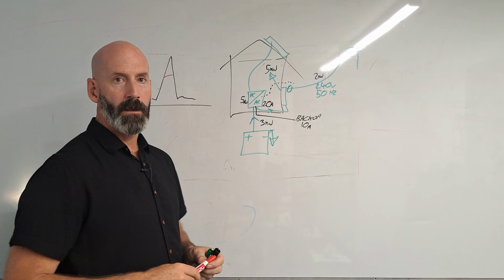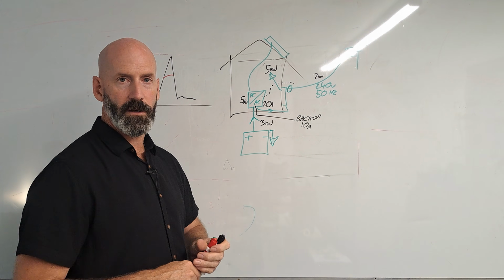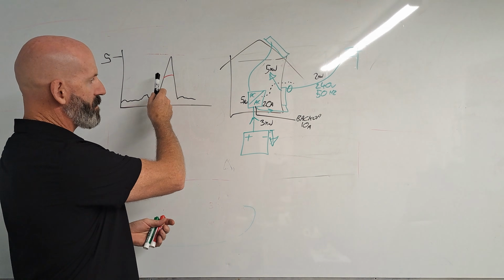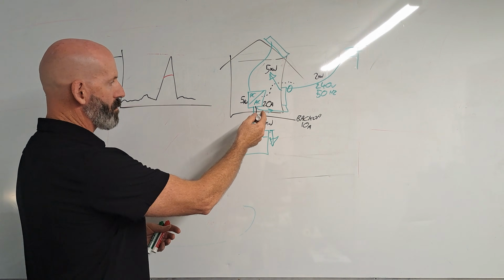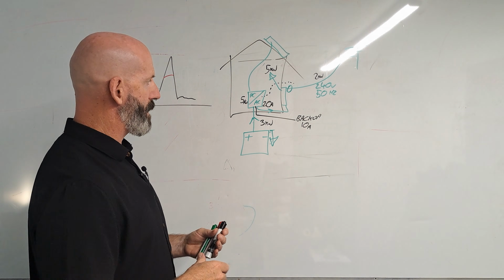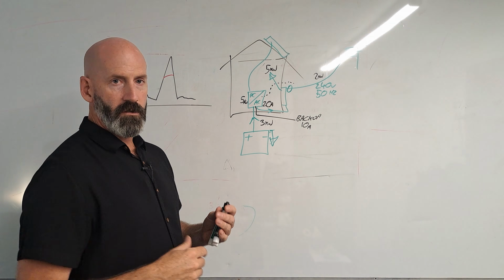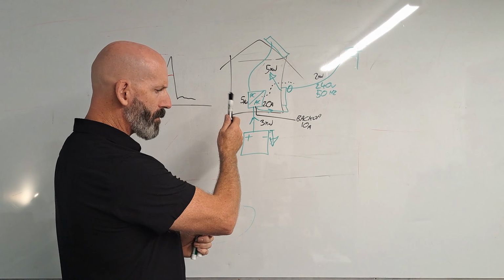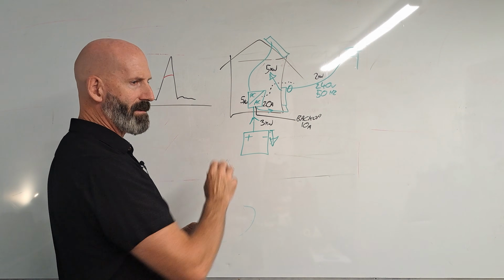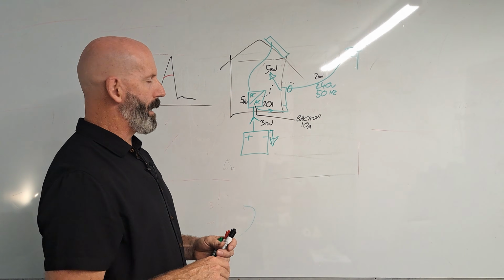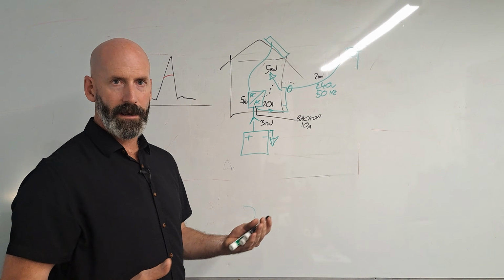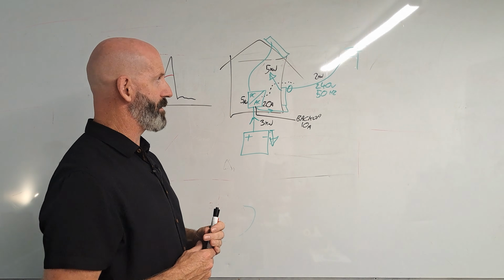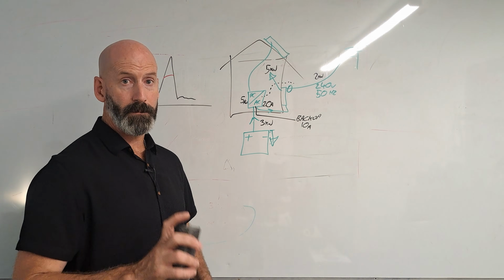That is to stop you from overloading that battery and the inverter when it needs to create that big spike of power. Because it's not designed to do this, it will limit how much power you can get out of that backup scenario. So you can't back up the full capacity of the inverter on most hybrid systems. There are some out there that you can get full capacity of the inverter on backup, but you've got to obviously get high-end equipment that can do that. Most of your mid-tier and below hybrid inverters can't do that. So that is some of the big limitations with hybrid.